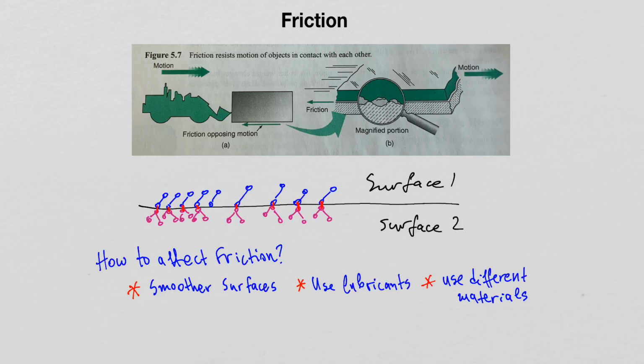So if you can make parts from Teflon instead of, let's say, steel, that will reduce friction. And of course, depending on the application, it's not always possible to use the smoothest, the slickest possible materials that produce the least amount of friction. But when suitable materials can be found, they can decrease the friction between parts.